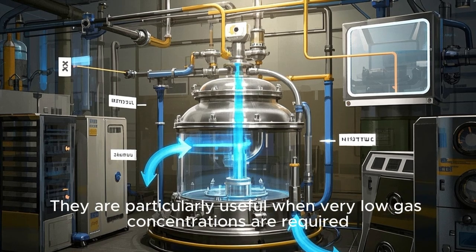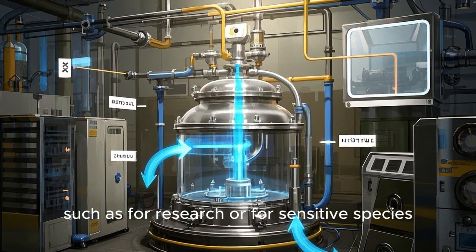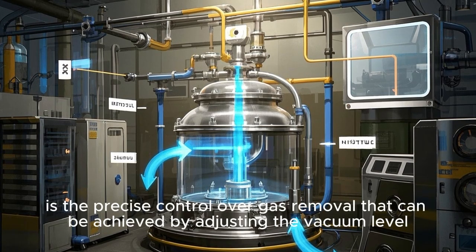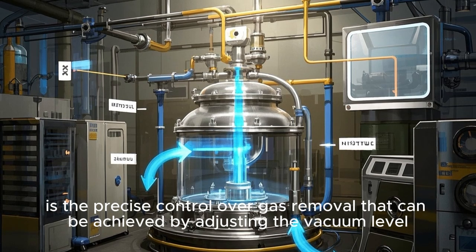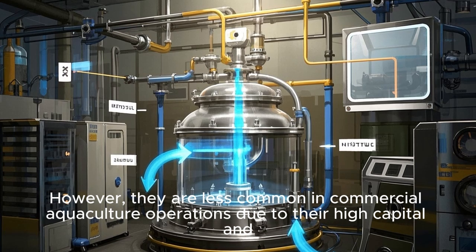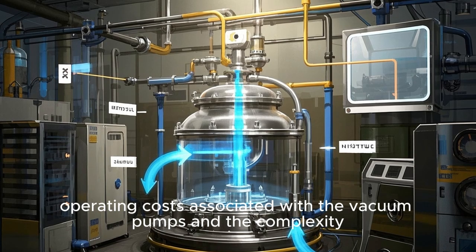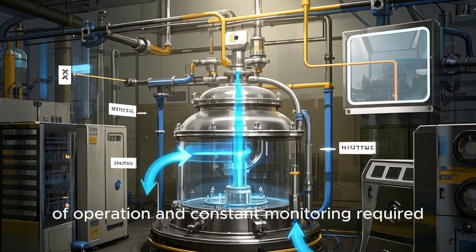They are particularly useful when very low gas concentrations are required, such as for research or for sensitive species. The main advantage of vacuum degassers is the precise control over gas removal that can be achieved by adjusting the vacuum level. However, they are less common in commercial aquaculture operations due to their high capital and operating costs associated with the vacuum pumps and the complexity of operation and constant monitoring required.